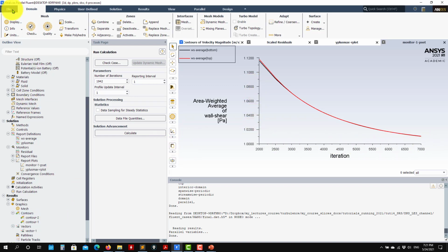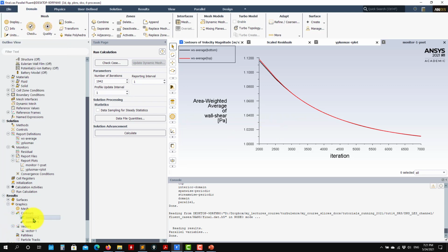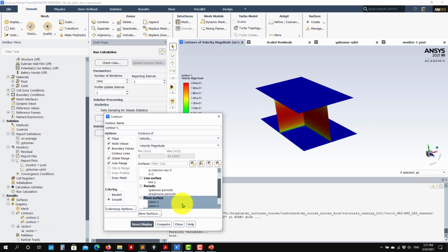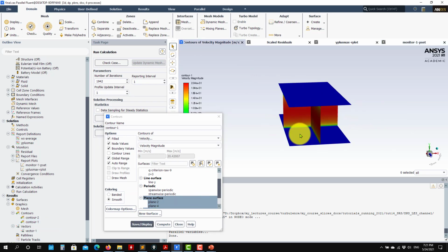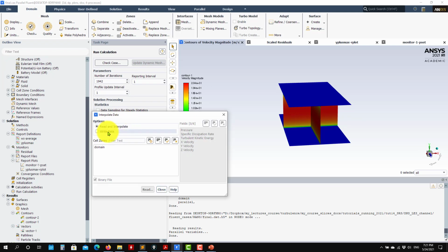But what is interesting, remember that to generate those interpolation fields, see that here we already have a solution. And this solution can be used as a starting point for the next one. It can be a coarser or finer mesh. So you can generate those interpolation fields. To generate, you go here, interpolate, and just write data, choose your data, and that's all.